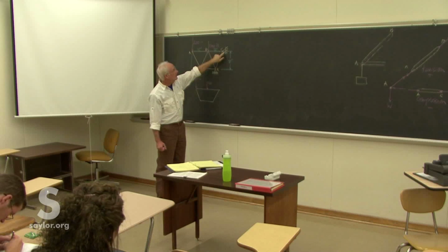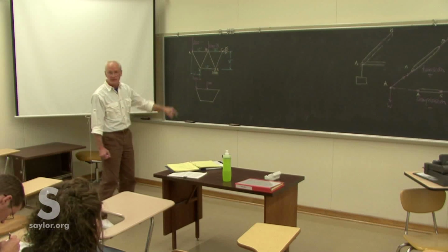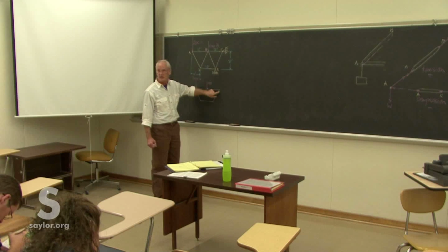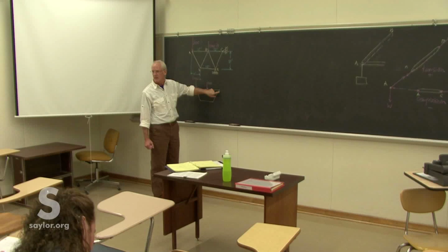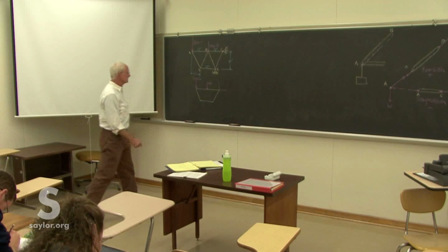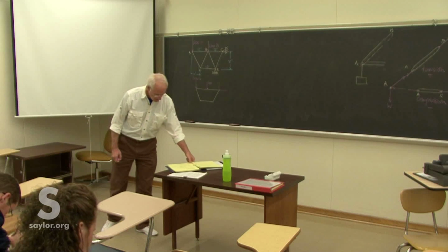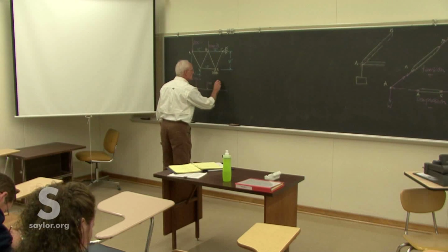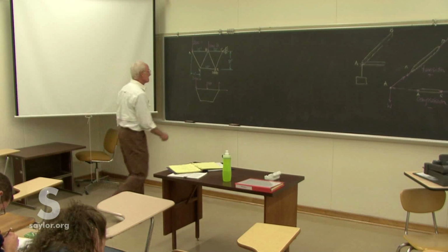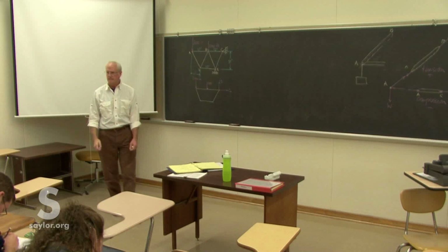Remember that the attachment itself is securely mounted on something, maybe a cliff or another building or something. So if I take out that support and I put in its reactions, what do I put? Force in the X and Y direction. Generally a force in the X and Y direction. Maybe we can determine something about the sense of those. Maybe we can't, so it doesn't really matter, because if we're wrong, we'll get a minus sign, as simple as that. So we'll call that CY and CX.